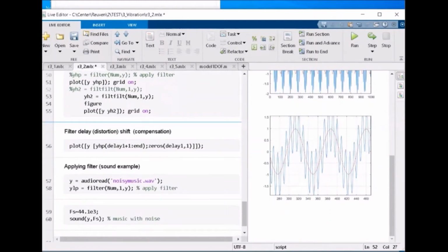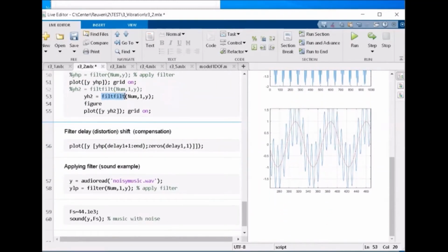Okay. If you don't need to use filter, or you cannot use it, you can use another way of getting these zero characteristics. It's just to start our signal from the delay. Usually the delay is the number, the half of the size of the filter.